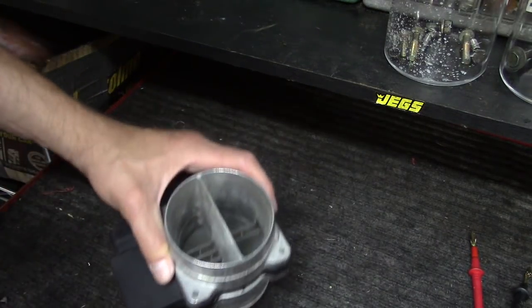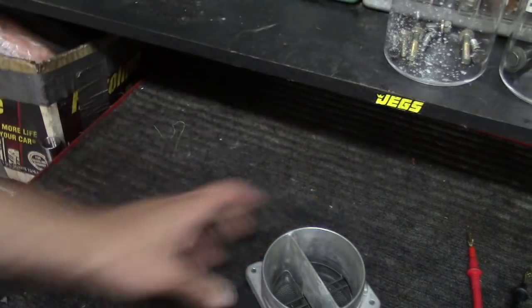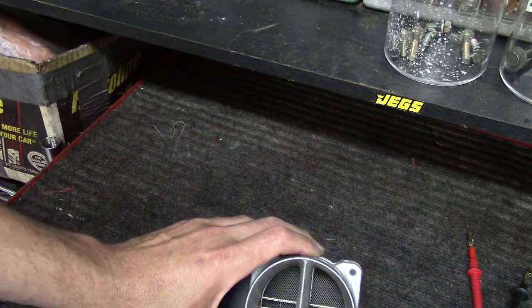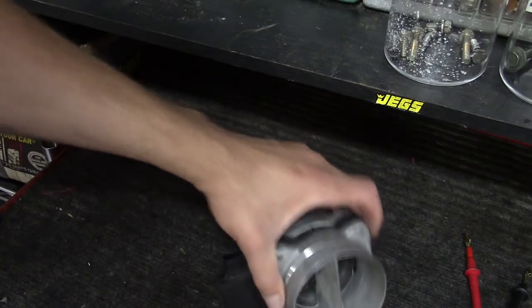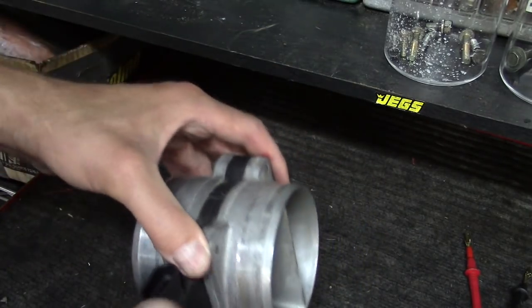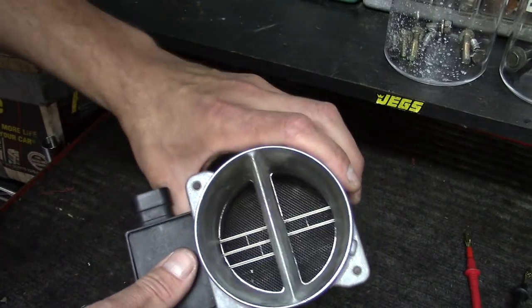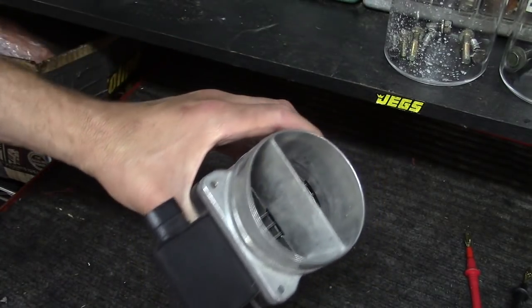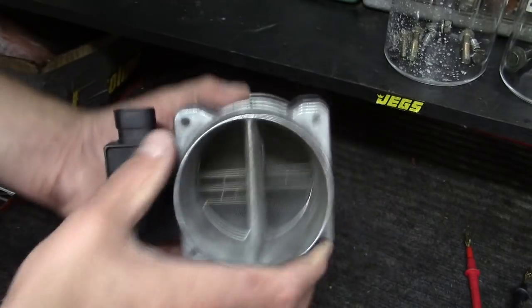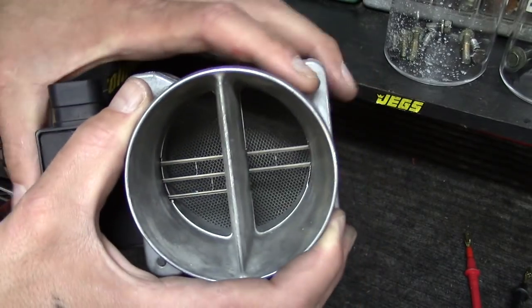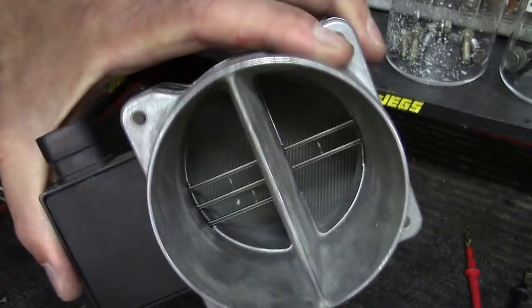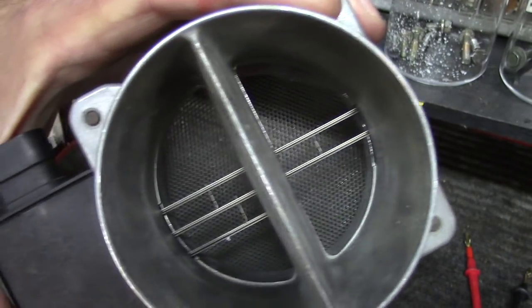But once you confirm that your wiring integrity is good, your next thing, you of course want to test the sensor itself. This is a GM 3-wire MAF sensor. This I actually think, if I remember, is one I've got from my Trans Am before I put the aftermarket one in. So obviously we haven't taken a look at one of these up close before, but you can see these little filaments in there with the little resistors.